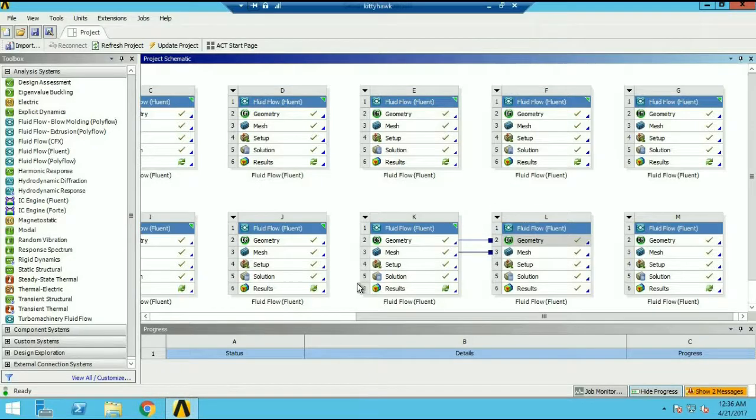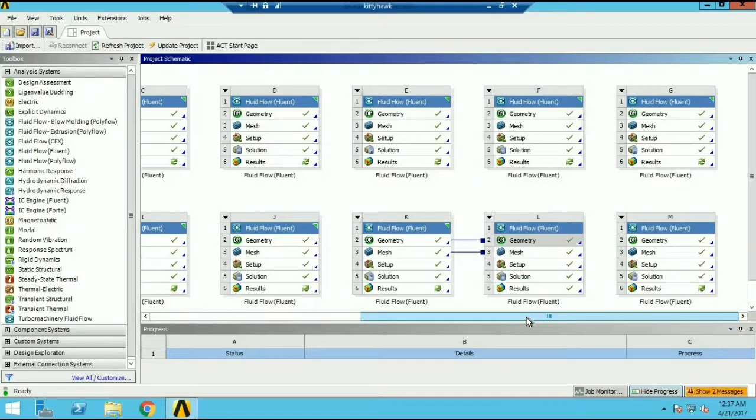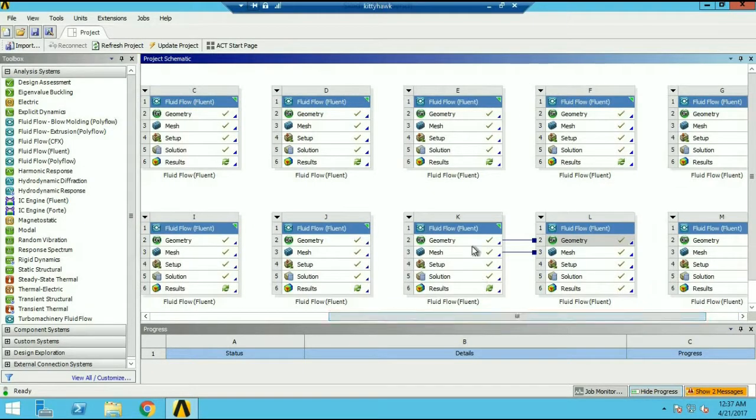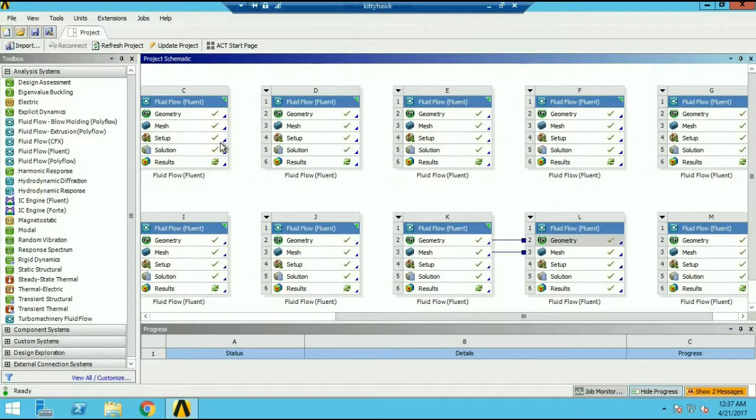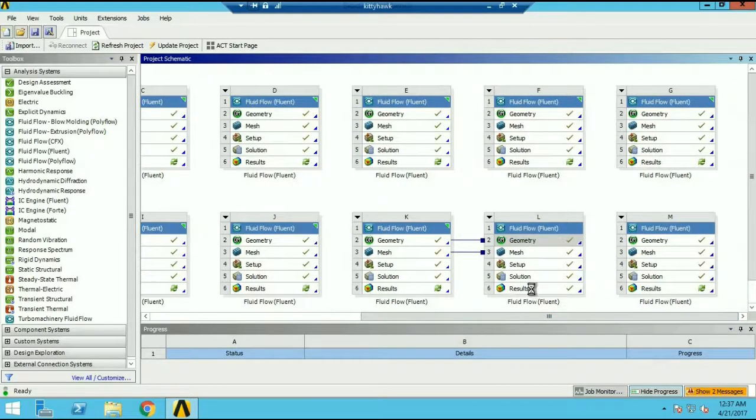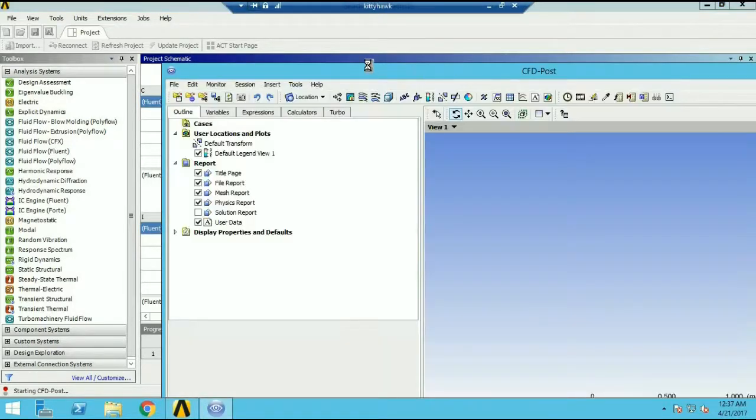So going back here. Also, I think I misspoke earlier. The XYZ forces are representative of lift, drag, because of the way the Cartesian coordinates are set up along the free stream. So Y will always be lift and X will be drag. So I misspoke earlier. We don't have to use the direction cosines to actually get the lift, which will make our analysis easier. So before we examine all of these, and to save you the trouble, I already took a picture of all of them. I'll bring up the results for the SST one, so we can just look around at what it looks like. It looks pretty cool.